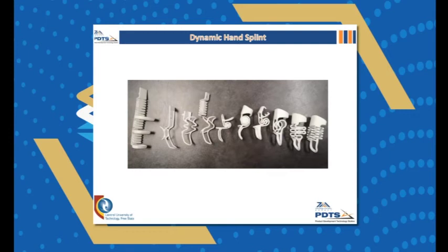The figure shows the different designs that were printed and tested along the development process until the desired one was created. Like mentioned before, product development is an iterative process. For the patient-specific dynamic hand splint, there were about 10 revisions that had to be made for the hand splint fingers. The reason for this was to try out different designs by using live hinges and exploiting the mechanical properties of 3D printed nylon parts to achieve the spring back you'll get on a normal hand splint.